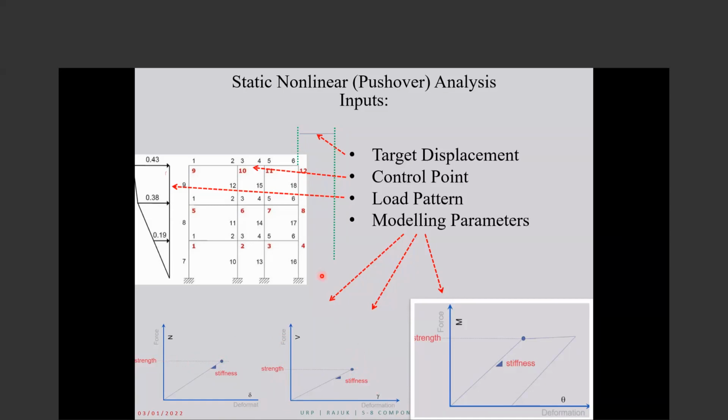The third one is that as you push, these force control actions come up but don't pass the limits. But the deformation control, like here bending moment versus bending deformation, if this passes, because it's a ductile behavior, it has some level of ductility.